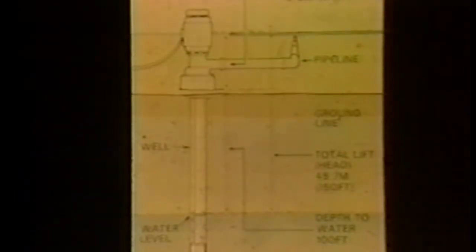In addition to the distance water must be pumped, the vertical height which water must be lifted or pumped determines pumping costs. The distance from water level to ground surface of deep wells should be added to the field elevation in determining total pumping lift or head. For surface water sources, the vertical distance from water level to the pump is also a part of the total pumping requirement. For centrifugal pumps, this distance should not exceed 15 feet.